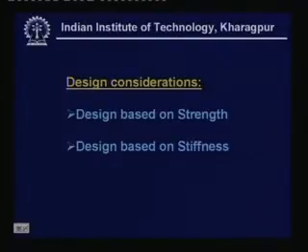In both cases, the tolerance level of either the deflection or the twist depends upon the use of the shaft. So, we consider the design based on strength at the beginning, and then we will discuss the design of the shaft based on stiffness.